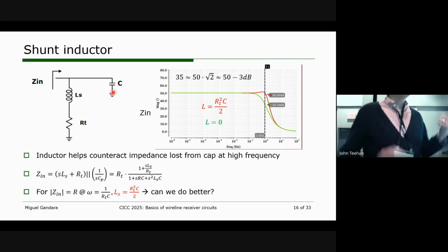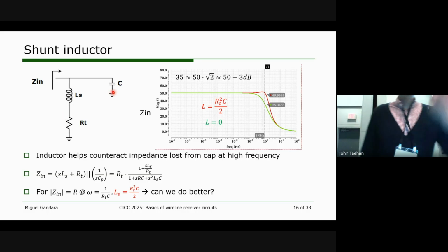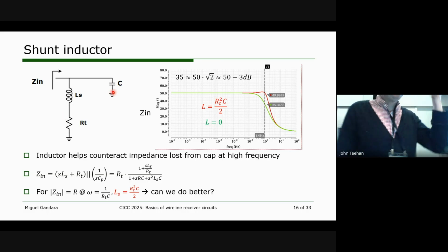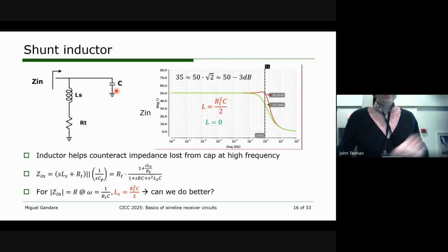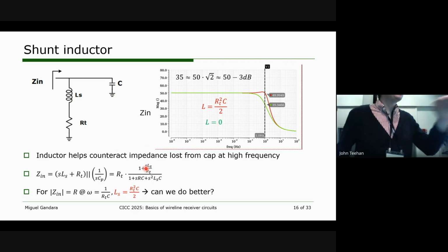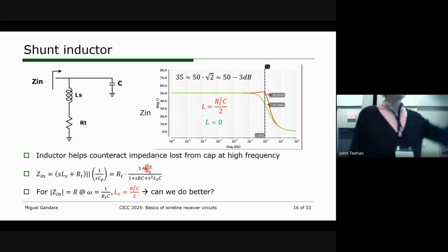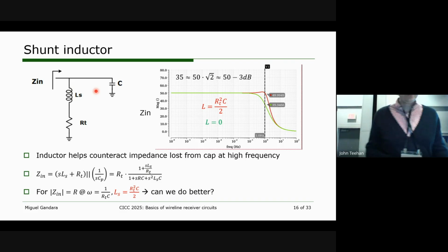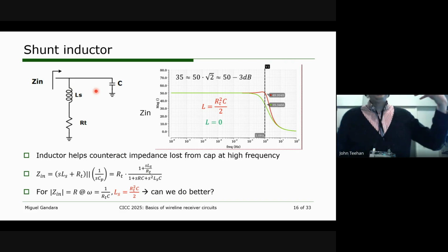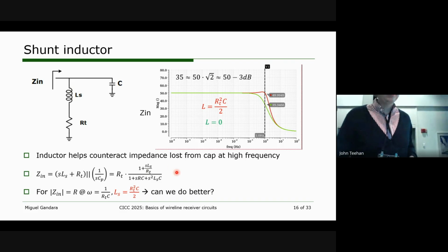with an impedance that decreases with frequency, okay? We know if two impedances are in parallel, the minimum impedance will always win, okay? So at high frequency, the cap will always win out. Therefore, the numerator cannot be higher order than the denominator. We must always end up converging to 0 for our impedance, because at the end of the day, at high frequency, we have a low impedance in parallel with a high impedance. Okay, so that's some intuition into why this expression comes out the way it does.